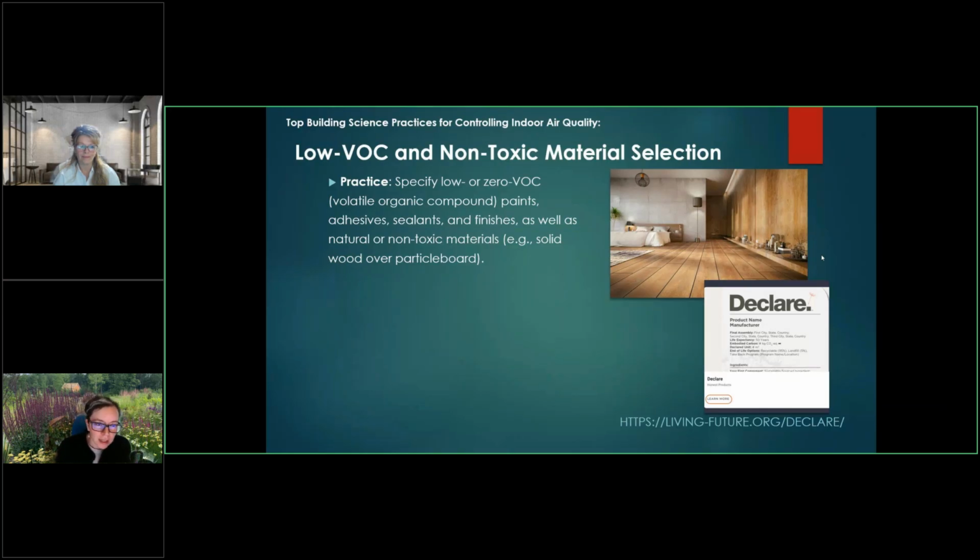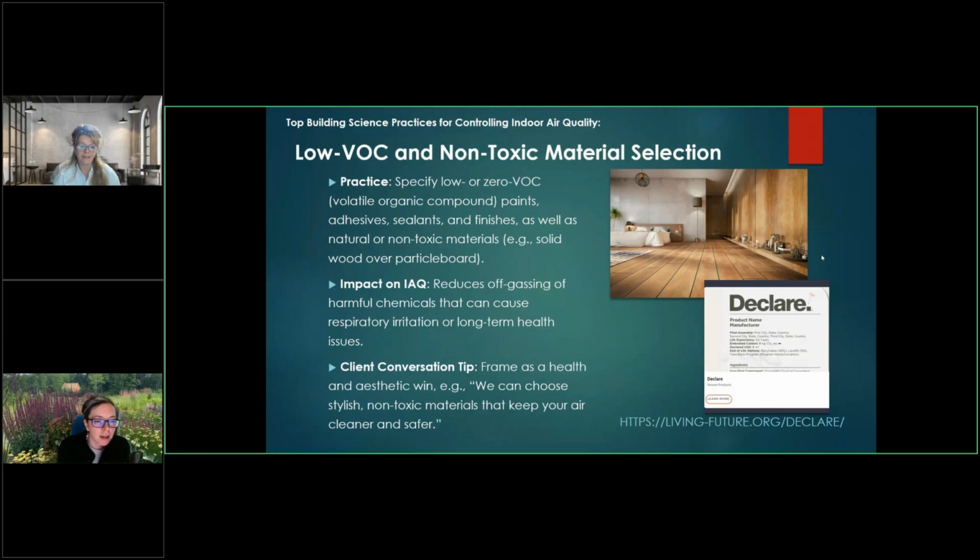We specify things that are low or zero VOCs where we can. That's adhesives, paints, sealants, finishes, as well as non-toxic materials like solid wood over your particle boards, anything that has to be kind of glued together, particle boards, plywood. We're going to reduce off-gassing of harmful chemicals that can cause respiratory irritation or long-term health issues. And then our tip that we do with our clients is frame it as health and aesthetics win-win. We can choose something that looks nice, that is non-toxic, and keeps it healthier and safer.